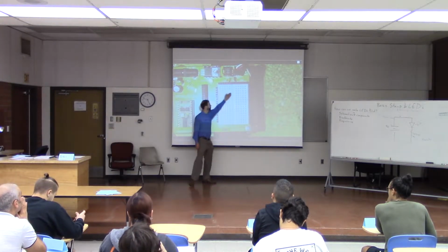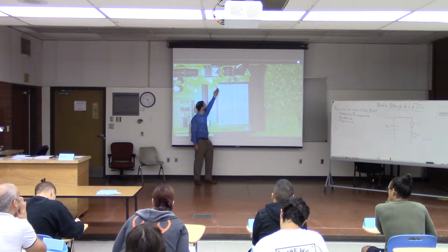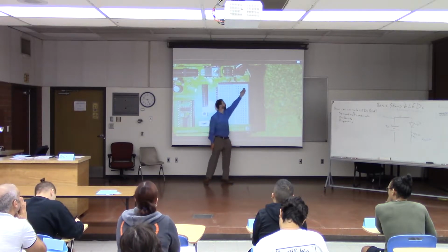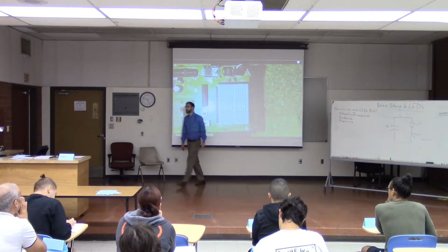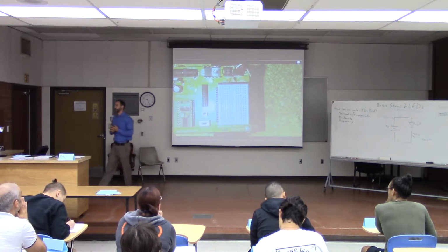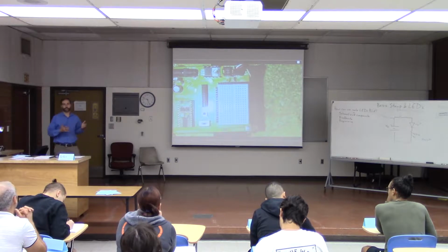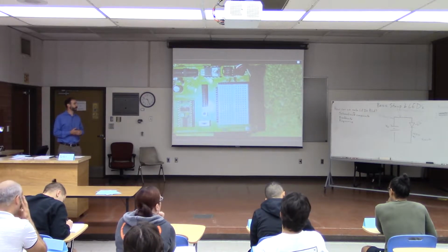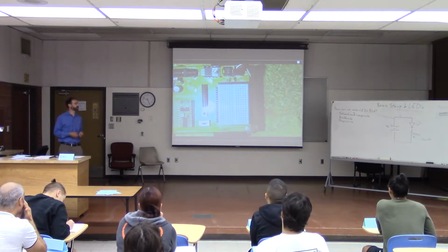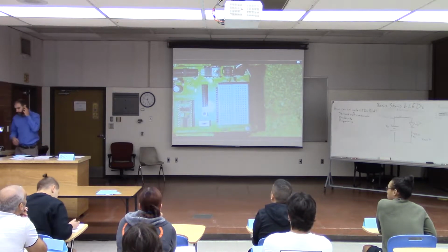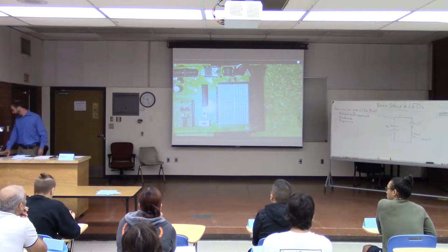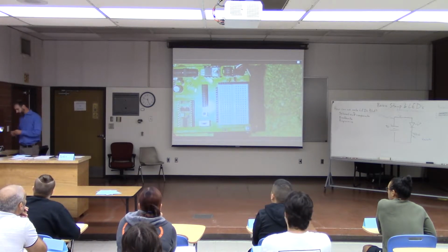So this is the breadboard that I was telling you about. You can see that there are the holes on the left, the holes on the right, and then this is the trough that runs down the middle. So this is sort of like our blank canvas. This is where we're going to start, and we're going to add the components that we need in order to make that circuit. So we can start with our LED.